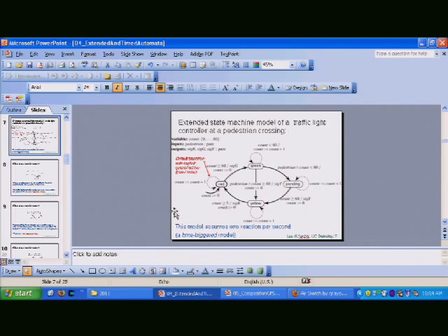Okay, I'm trying to understand the question. The model you create here is certainly an abstraction of the code, right? But when you're coding, you're implementing some state machine as a program. If you take that switch statement and all the variables there are finite, then what you have is another state machine. It may not correspond to this bubble model exactly, but if you took your model state machine and implemented that directly, it should correspond. That's right. But what you should do is make sure that if the assumption is that a transition is instantaneous here, then a corresponding transition there is also instantaneous.